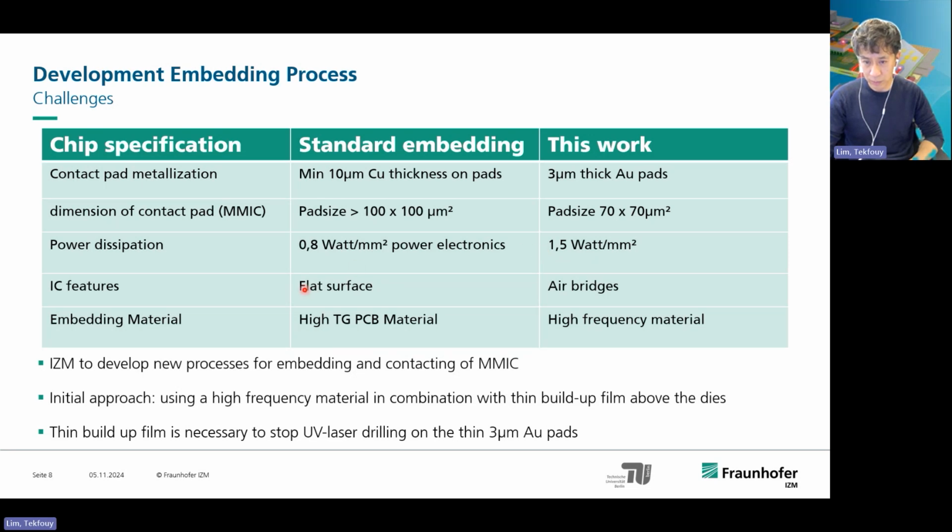And the ICs also have some air bridges, which makes the integration a bit more tricky because any air pressure can destroy the air bridges. So we have to make sure that the air bridges are well preserved after the embedding process.